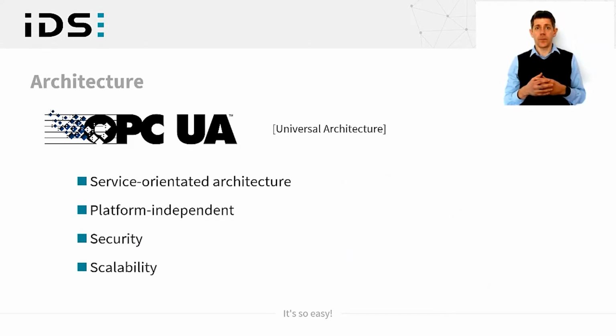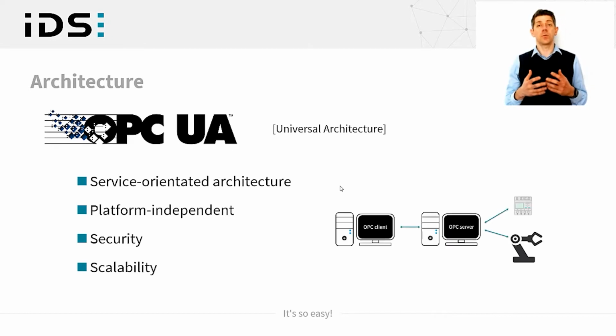The architecture of OPC UA builds on the original server-client relationship that was introduced with OPC. An OPC UA server will respond to requests and provide data to any number of clients based on this publisher-subscriber model. This means that messages are only sent and received between devices in the network that are interested in the message, in what the message might contain. So this means it achieves excellent network efficiency. And the client server structure allows the use of any number of network topologies.